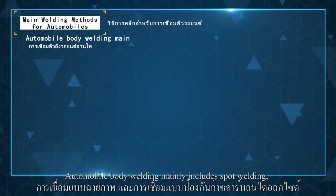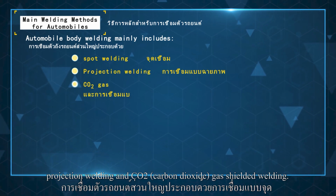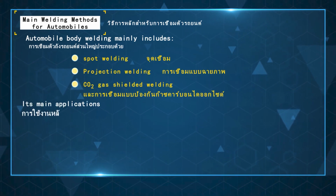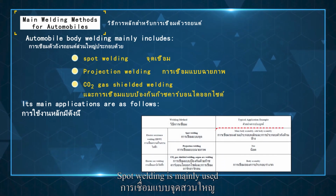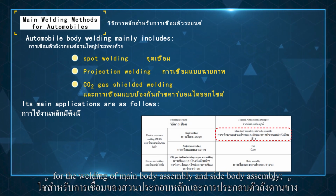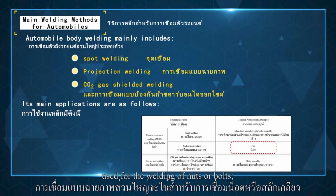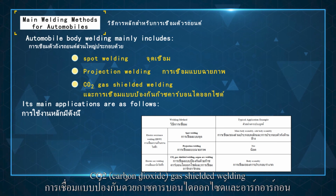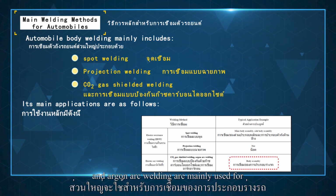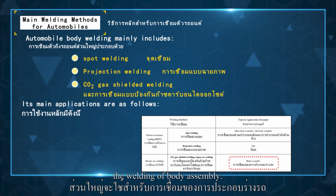Automobile body welding mainly includes spot welding, projection welding, and carbon dioxide gas shield welding. Spot welding is mainly used for the welding of the body assembly and side body assembly. Projection welding is mainly used for the welding of nuts and bolts. Carbon dioxide gas shield welding and argon arc welding are mainly used for the welding of the body assembly.